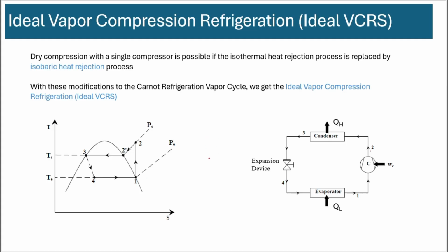So instead of using two compressors, we have one compressor and we are operating between, again, these two temperatures. But there is another temperature here. We can call it, for example, discharge temperature, okay? So that's actually the highest temperature in this diagram. So you actually go higher than the actual condenser temperature and then come down to the actual condensing temperature.